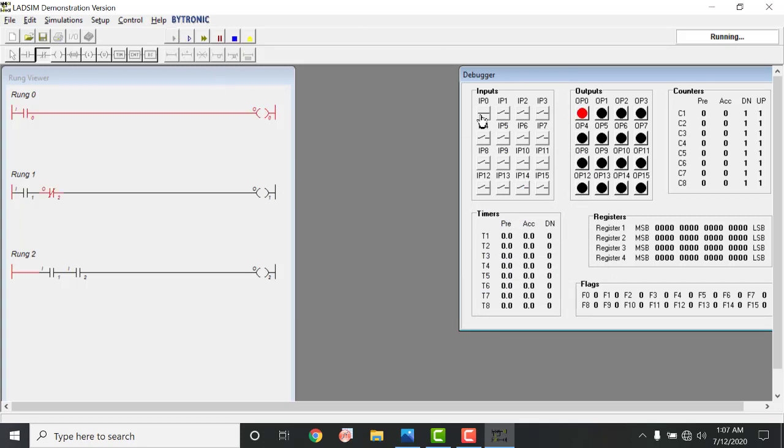Now you can see the conveyor belt running, metal sensor detected, and it would allow the solenoid valve to push it, and when these two signals are working at the same time, meaning metal is detected, it would stop that pushing and let that material bypass through that channel. So a normally closed contact is used where you want your process to reverse, so that's how we are dealing with it.